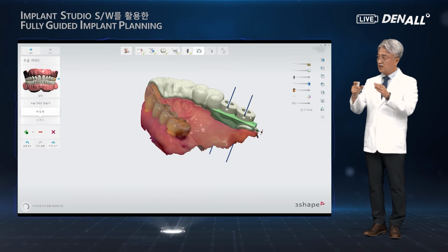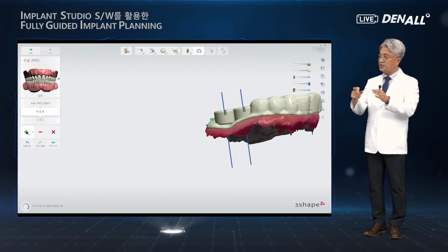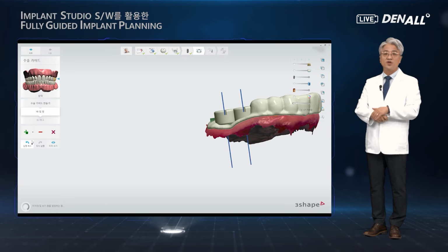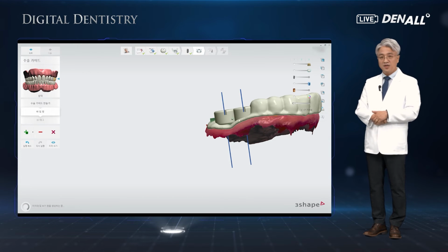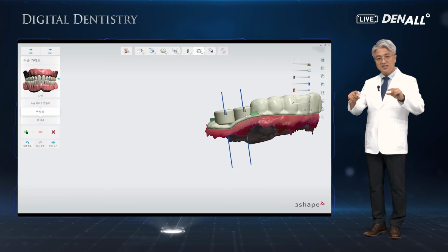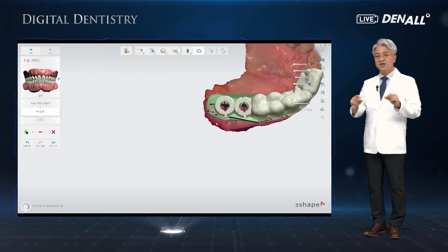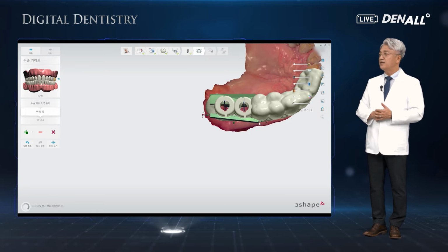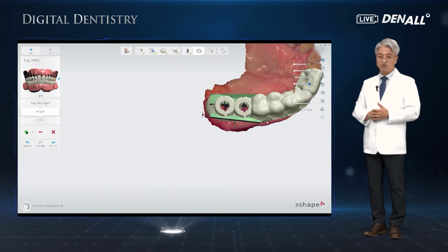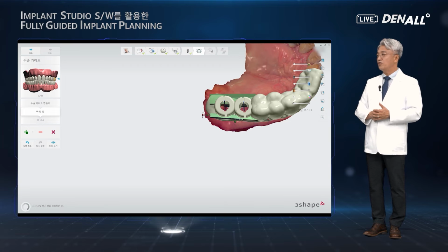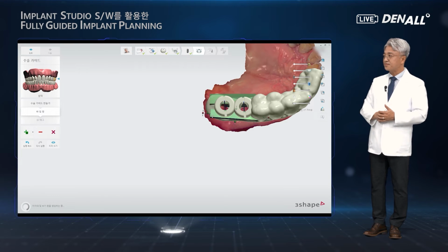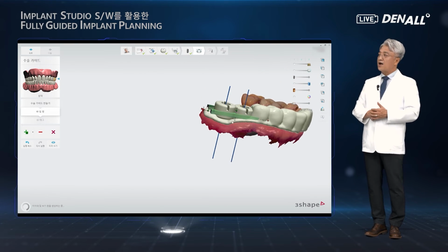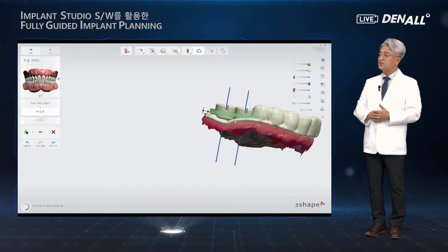Now the bar is generated. In the sleeve hole portion, resin is very thin and you need to reinforce it to make it rigid to prevent fracture or bending. So bar is added to enforce that. Now the bar is made.